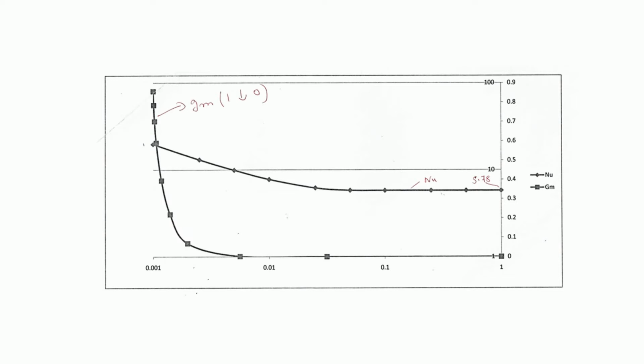So this is the key value, and of course, in the PPT we can show how the entire thing actually works. As you can see, this is the mixed mean temperature, and this is the corresponding value of the Nusselt number. Once again, it starts off pretty high at around x bar equal to 0.1, and it slowly asymptotes to the value of about 5.7831. After that it is constant, because that is the thermally developed regime.